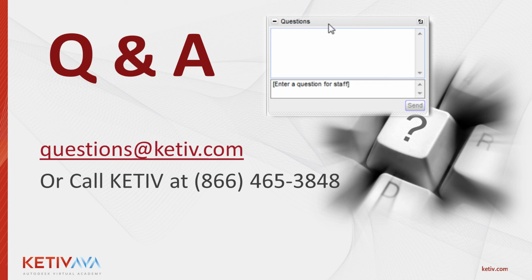First one, is there a way for Inventor API to search a Vault database for existing components? Okay, so the iLogic and really the Inventor API, its scope is Inventor. Vault has its own API. Now that's not to say that you can't create a .NET add-in and use the Inventor API and the Vault API together. But you would really have to create that to accomplish that. iLogic has no capability to interface with the Vault API.